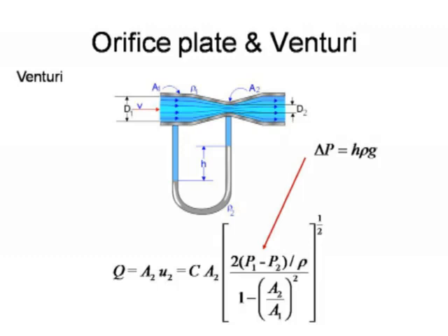Of course we can now substitute in for P1 minus P2, the pressure difference, and we can substitute in the equation depth times density, the static head equation. If we do that, we can then cancel the density terms out, but that sort of hides the secret, because if we do that, bearing in mind the density in the square brackets has come from Bernoulli's equation, that's the density of the process fluid, the fluid flowing through the venturi or the orifice plate.